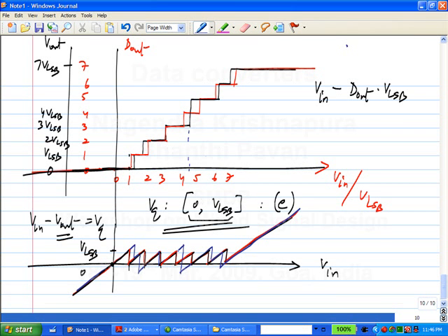Okay. Now this is because we were not able to place the transition points accurately. Now, why exactly that may happen, we will see later, but generally you will not be able to place the transition points exactly where you want them to be. Okay. Now, this error is a different type from quantization error. In that quantization error, everything was ideal, still you are getting error simply because of the rounding process. Now, this is because of my inability to make the transition points. So, this is an error in the design or some kind of non-ideality in the design. Okay. So, the result is because of the shift in transition points, the range of the quantization error increases.